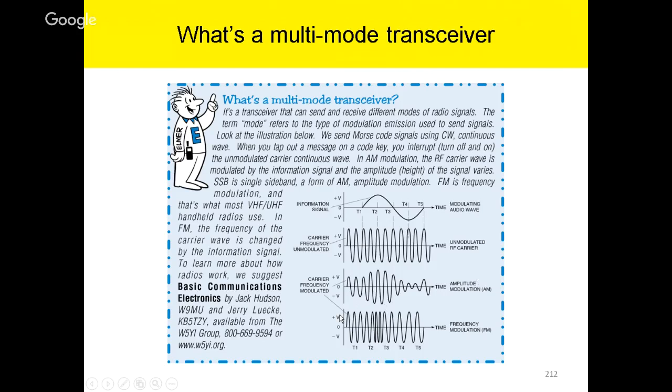Conversely, when you're modulating an FM signal, it actually changes the frequency of the signal, so that it's not a dead carrier frequency, but it's actually changing within a few kilohertz of your carrier frequency. And the width of that, if you remember back before, for an FM signal is 10 to 15 kilohertz, typically.